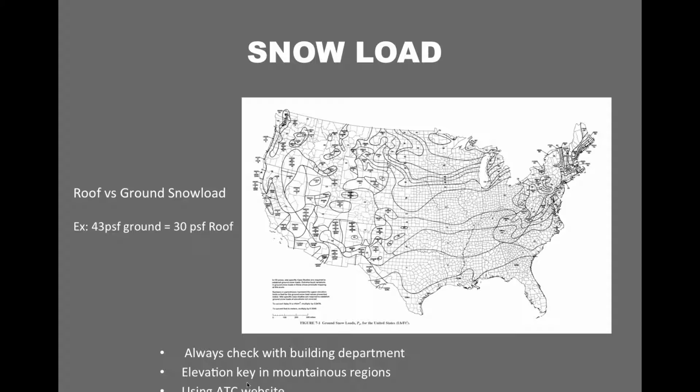Yep, went over all this stuff. And then again, further on in the course, there is a website that will allow you to enter your job site address, and it will give you, for the most part, a pretty accurate snow load number there. Again, unless you're in mountainous areas where there is varying snow load depending on elevation.